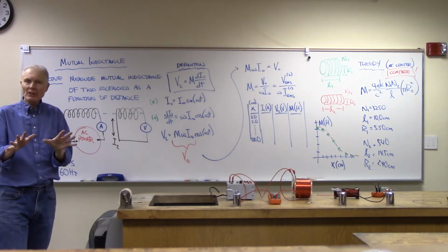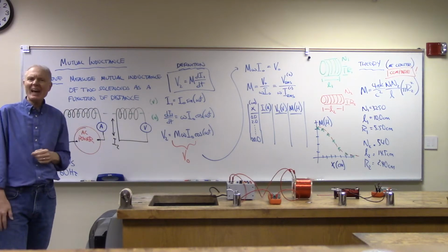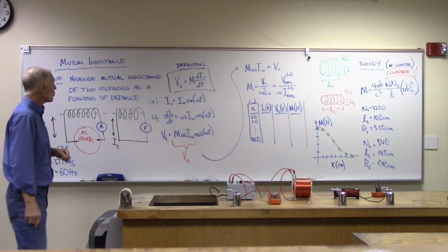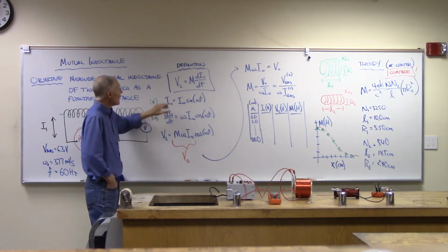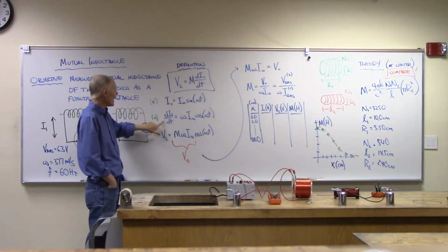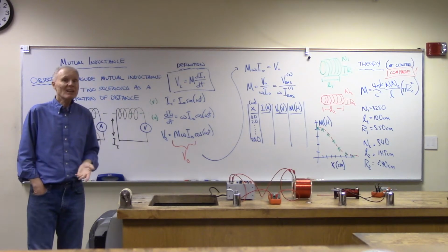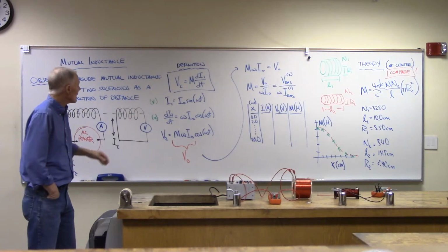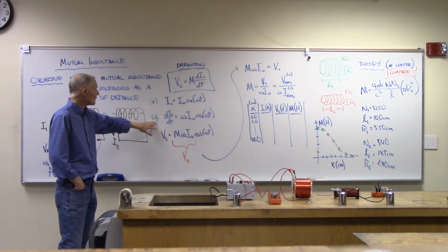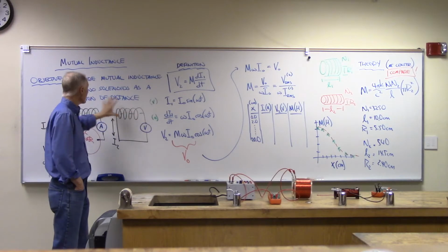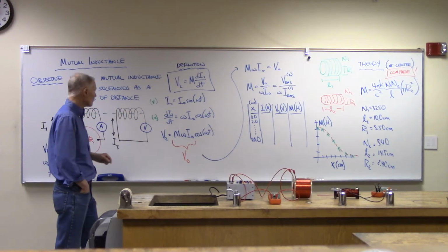Now they're not moving with constant velocity, but there's kind of an average velocity at which the charges are moving. And since this is varying, there's also an acceleration. So di/dt is going to tell us something about the average acceleration of the charges. And it's the electric fields generated through accelerating charges that create this effect.